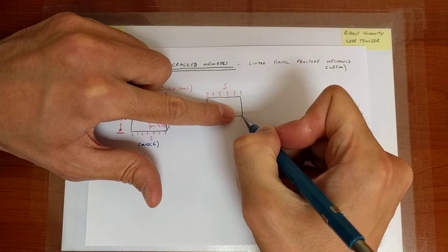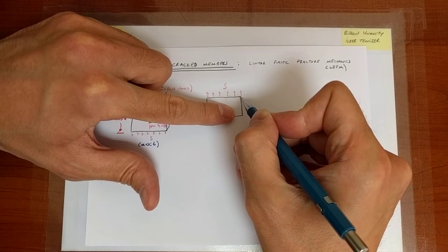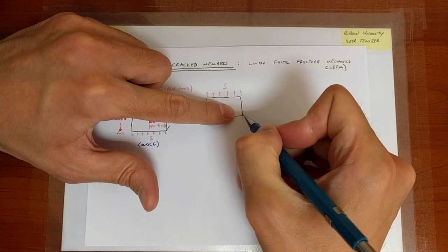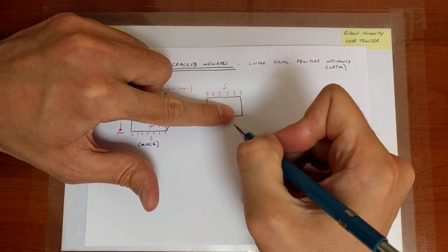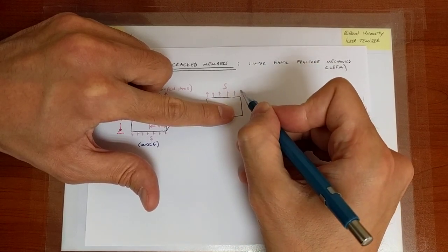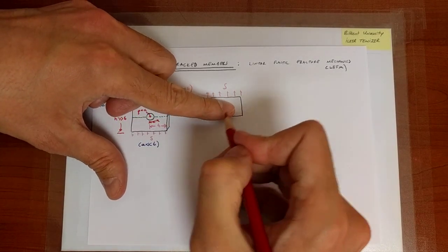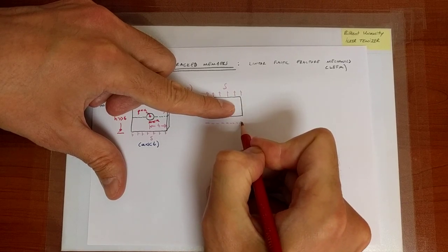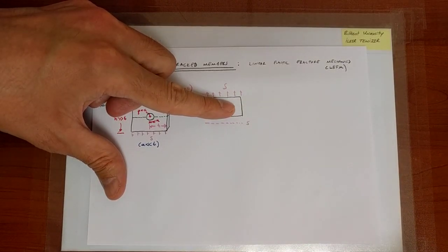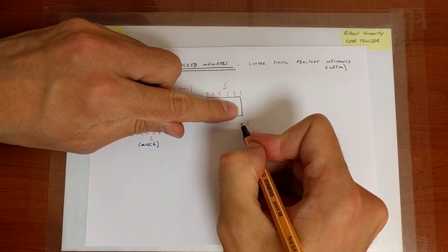So the points here are going to experience a normal stress that is the same as the normal stress a little bit further up on the plate. The idea is that these points do not feel the presence of the hole, so they think that the plate is a perfect plate with no hole in it, and therefore the stress would be uniform. Because that's an expectation, let us indicate the level of S with this red line. That's where S is, and that's where my actual stress field is going to start from.